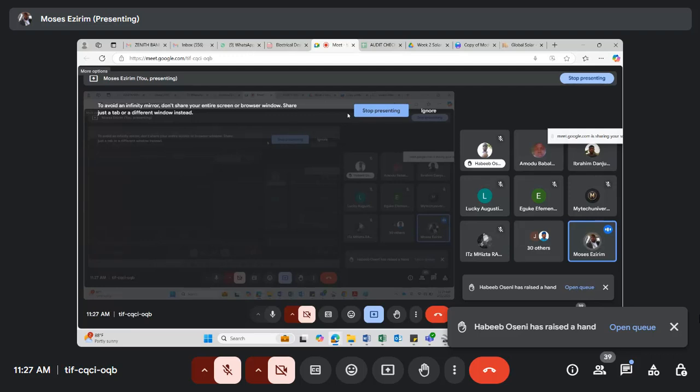Victron doesn't have a solar inverter. They don't have a PV inverter. What they have is a battery inverter. I'm sure that once they have a solar inverter, that principle will change. But as for now, they don't have a solar inverter. So their battery inverter has a compatibility issue with Fronius, Solar Edge, SMA, Huawei.